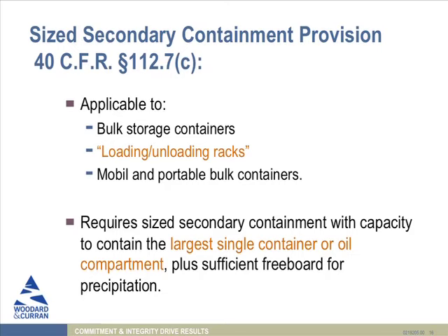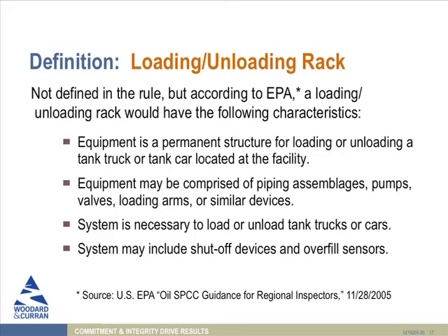So just to back up again, because another one of the things, does anyone know if they have a loading or unloading rack? They're not common, but if you were to have a loading or unloading rack at your facility, it would be subject to this size secondary containment requirement too. And just to give you a little bit of a description here, it is not currently defined in the oil SPCC rule what a loading or unloading rack is. It just mentions it in one of the regulations.